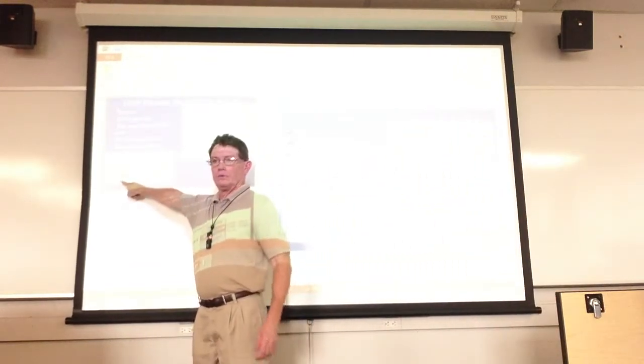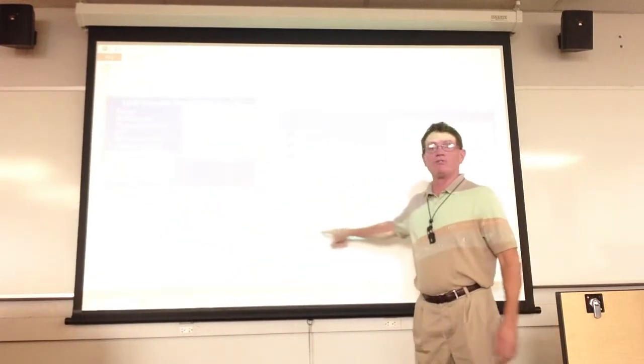You can run it on the 169, even though you're using port C? Oh, it's running on the 2560. Yeah, sorry about that. Or the 32, either. Does the 169 only have 2 ports? On the Butterfly board, you only have access to port C and port D. That's what I was trying to show you on the slides. That's what physically you can get your hands on. That's why we have to use the 2560, or the 32.